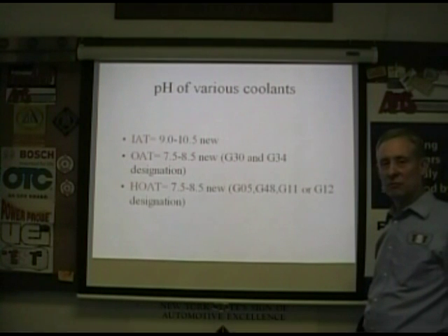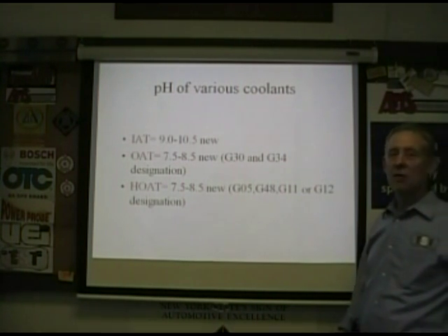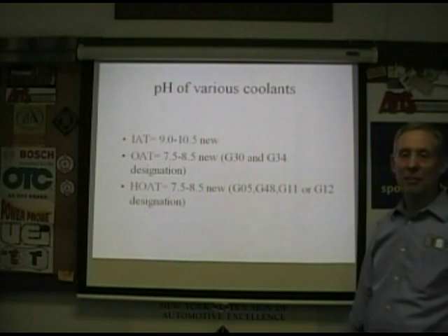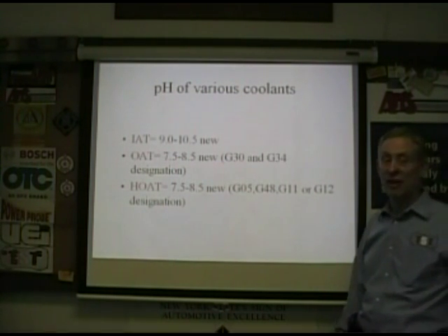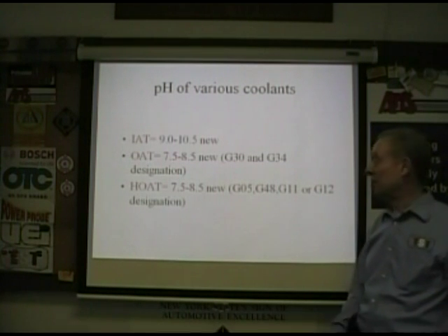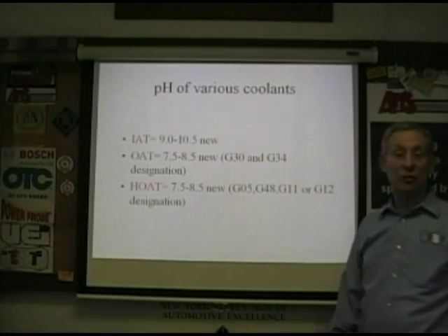Try to use the correct antifreeze or coolant, however you want to say it, meeting the spec, and use the strips to see if they're good. That's right. Test it. There are also machines to test pH and so forth, not just strips, but the strips are there for the chemistry. And check your water to make sure it's good water.